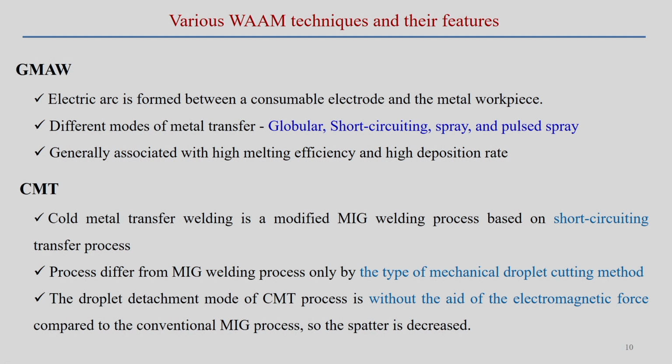Now, if we look into the direct energy deposition techniques, the wire arc additive manufacturing process has been developed based on this concept. Wire arc additive manufacturing simply utilizes the same principle of material deposition that occurs in the welding process, so the same welding machines can be utilized. Normally, plasma arc welding can be utilized for developing wire arc additive manufacturing, but in that case there is a need to feed external material in the form of a wire, and the plasma source melts the wire and deposits the material on the structure.